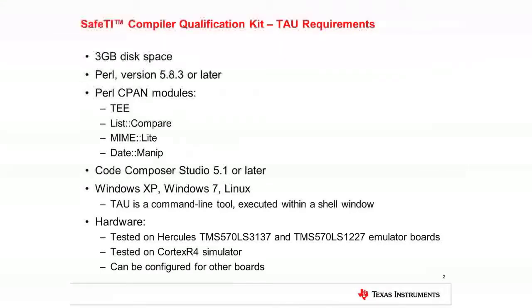The TAU will run on Windows XP, Windows 7, or Linux. The TAU is a command line tool and will be executed from a shell window, such as a DOS shell. The TAU has been tested on several Hercules boards, including the TMS570 LS3137 and TMS570 LS1227 emulator boards.